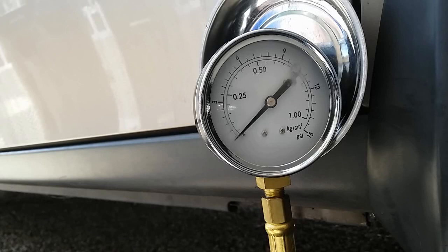And then once you crank the engine, the next step is to raise the RPM to 3000. The spec for 3000 RPM is basically no more than 2 PSI of back pressure. On a good catalytic converter, it should be less than 2 PSI.